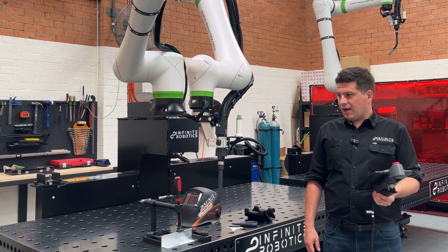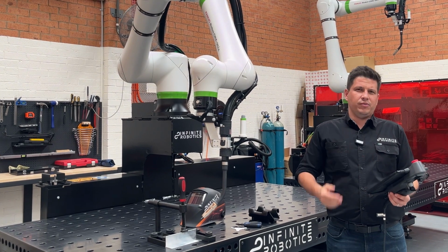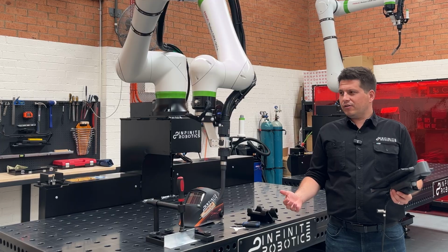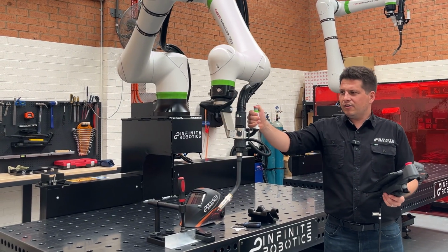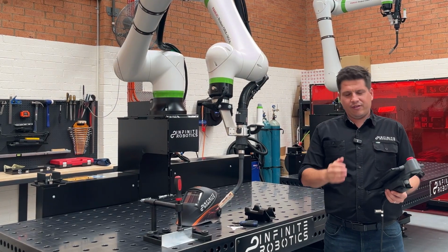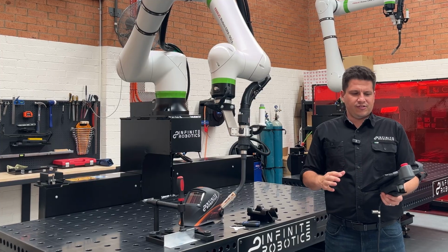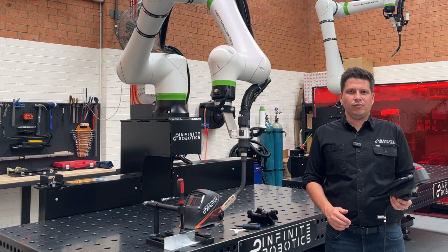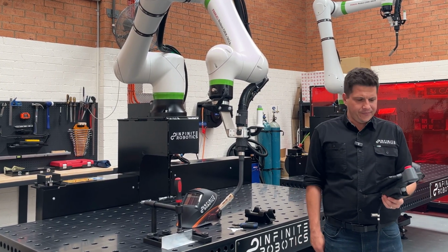And then we generally just need to move the robot where we need it to and record the position on the tablet Teach Pendant. The great thing about cobots as well is you can move them around with your hands, so they're very tactile. And then also there's really no programming on the tablet Teach Pendant. It's very graphical. It's just a case of dragging the icon onto the screen that corresponds with what you need to do with the robot, such as recording an air move or a welding command.